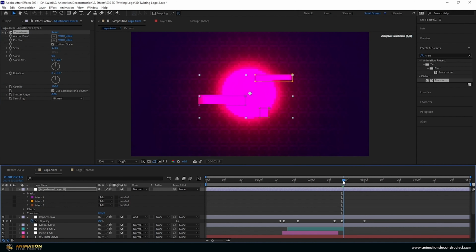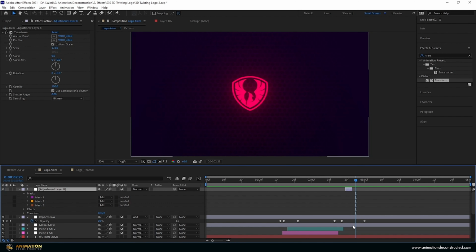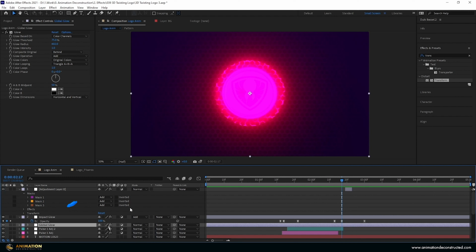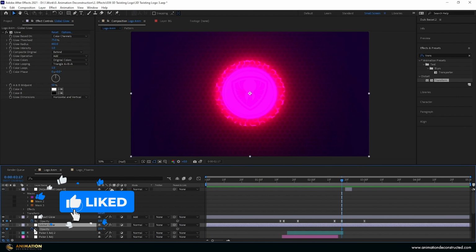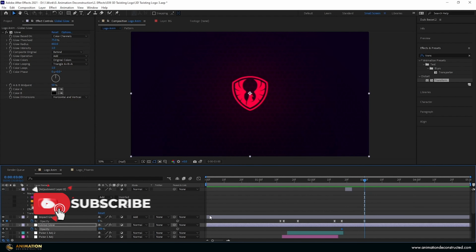Let's move over to about 219, and that's fading out, and just bring this in over here and leave this for about 3 frames. And then it's up to you to actually take that global glow down just by pressing the T key, adding an opacity, and take it off. Let's say at about 3 seconds.